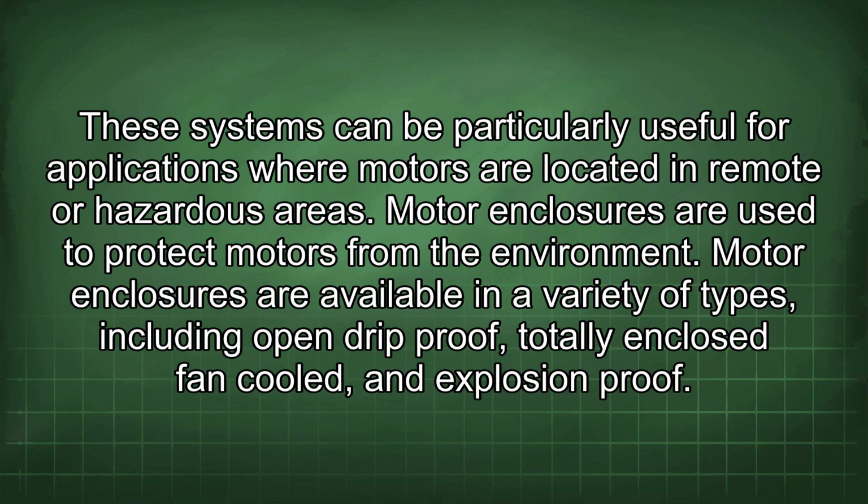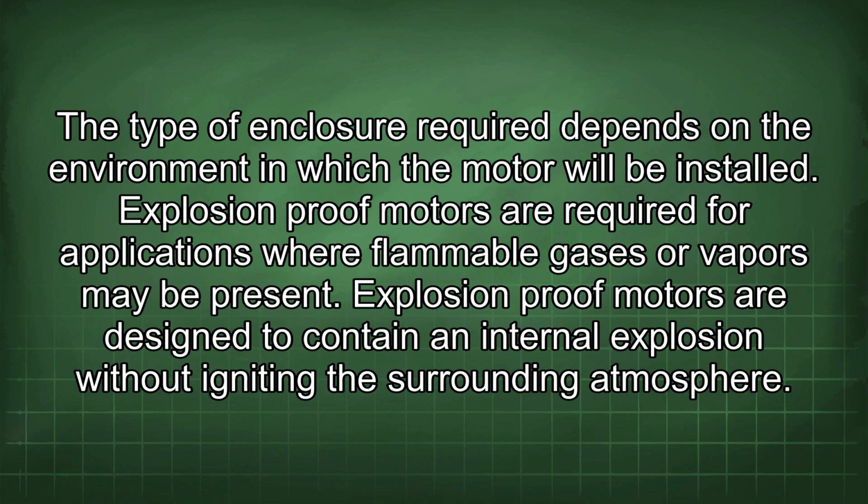Motor enclosures are used to protect motors from the environment. Motor enclosures are available in a variety of types, including open drip-proof, totally enclosed fan-cooled, and explosion-proof. The type of enclosure required depends on the environment in which the motor will be installed.